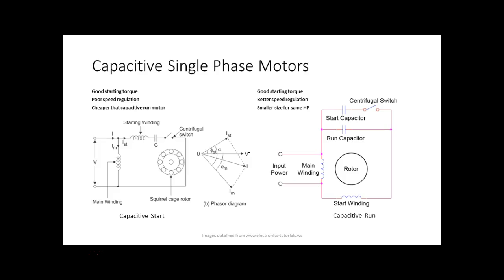I had a swimming pool, and it sat there and hummed at me. What did I take for granted? And I didn't even check it, guys. You can check a big capacitor. I'll have to show y'all that. You can actually see the capacitor charge up with an ohmmeter. So you can put it across there, and then you can see it charge up to overload. I didn't even check it out. I took for granted it was a capacitor.